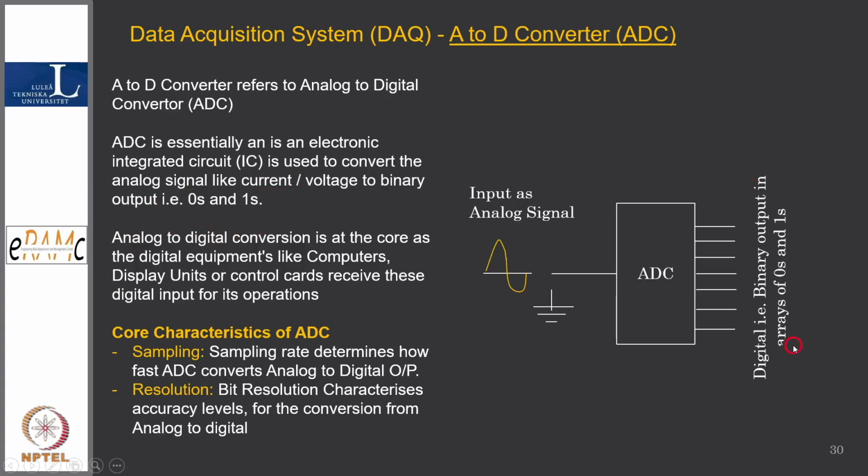So the signal is going in the form of a 0 and 1 stream, and if we feed it to the computer, then we can draw a graph and see the characteristics, how the vibration is varying, and which frequencies are dominating. If I know those dominating frequencies, then I will know whether it is an inner race failure or an outer race failure. I am talking about a mechanical component, but the same thing applies for an electronic component also. So in short, we are using this signal to assess the failure characteristic, and how severe the failure is. And of course, the domain knowledge will tell us which signature tells what.